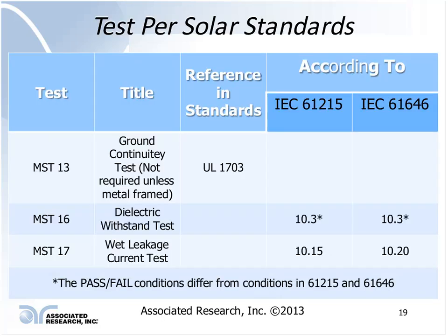Now let's get into the standards a little bit, because there are main ones I want to cover here. The main standards that I usually look at when I'm dealing with solar panel stuff are UL1703, IEC or EN 61730, 61215, and 61646. You might notice that I didn't list 61730 on here.